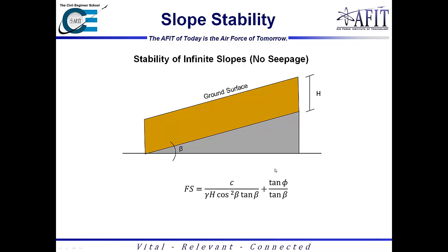This also gets into what's sometimes called the angle of repose. Say this was a sand layer and I increase the incline above the internal friction angle; this is going to slide off and fall. However, if I maintain the inclined angle below the friction angle, I'll maintain a factor of safety. Conversely, if I have a soil that has almost no internal friction but has high cohesion, then I'll only be dealing with this term here. So with clay, as is typically the case, we assume the friction is zero. However, with sand, it's typically the opposite, where we assume cohesion is practically zero and the friction angle governs.